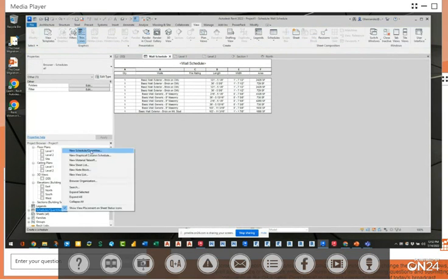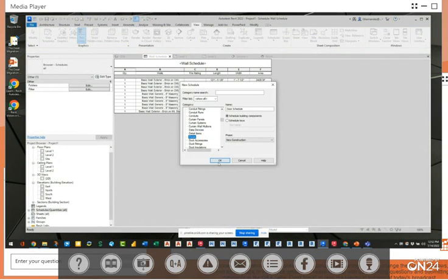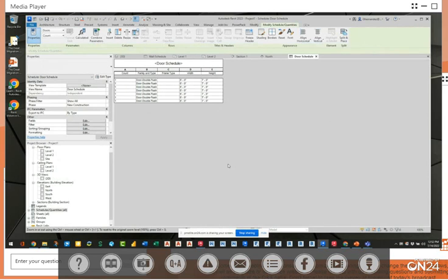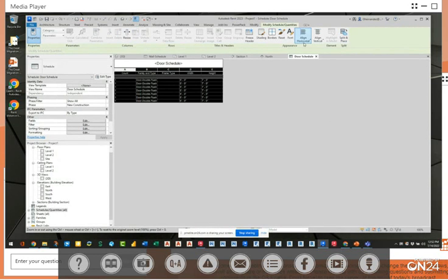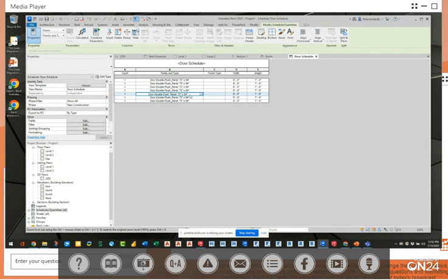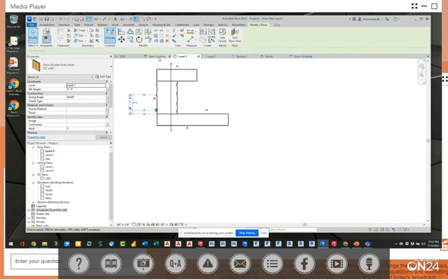I can go back in and go into the door schedule and do the same thing. Go to count, family and type, frame type, width, height, and I'm done. Right. Now, again, the focus on the database part of this and what makes this a little bit better to kind of make the transition into is this right here.